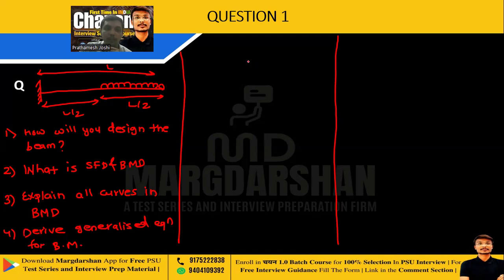So if the length of the beam is large enough, shear force will not cause that much trouble, then the bending moment will have a major role. But if the length of the beam is not that large, we have to think about the shear force also. Then we will design the diameter, or say length and breadth, on that particular section appropriately. So this is how the beam can be designed.